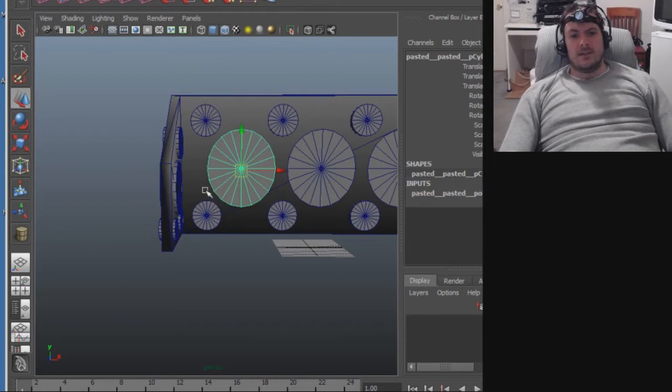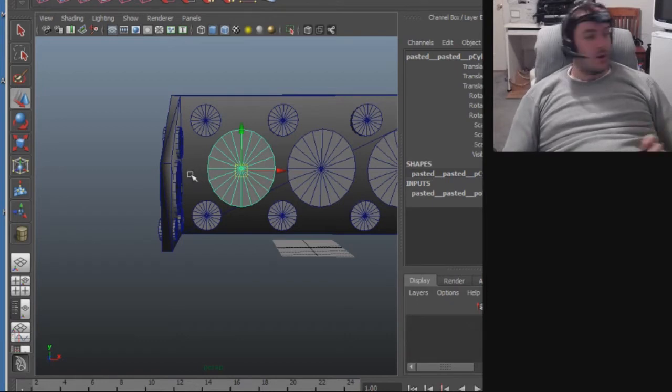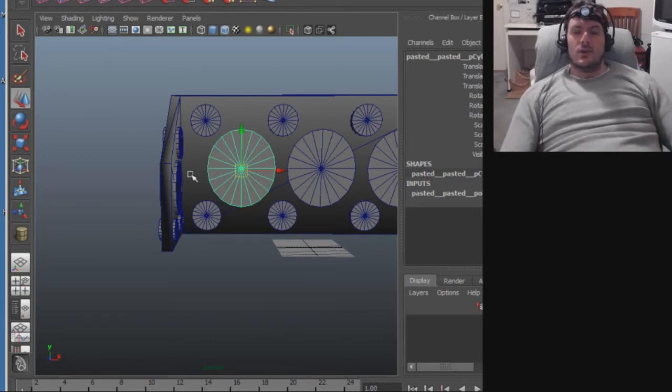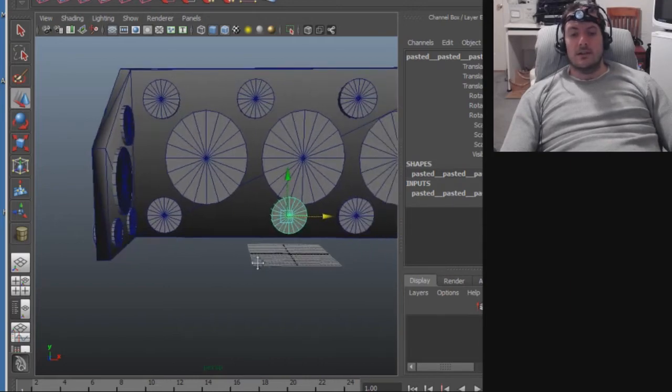So you're going to want to make sure there's plenty of thickness between these circles and never a gap wider than, I mean, you never want a gap between circles to be more than approximately 2.5 centimeters. If it's more than 2.5 centimeters in width, so like if I move this one over here, that would be enough to create a crack or delamination and possibly even warp the bottom right here, as this long string of layers, layer after layer, pulls upward on these lower layers that will cool faster. These will peel upward. So you don't want to have too much gap here, otherwise you're running into the same problem that this whole thing's supposed to solve.